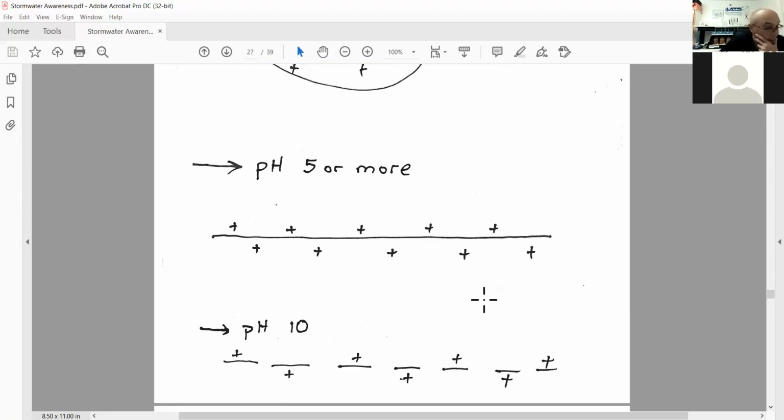So chitosan is pH sensitive and therefore needs to be used in pH ranges that are conducive to construction stormwater discharge requirements. When pH is 9 or above, chitosan will not work as well as at 8.5. At pH 10, the molecule is severed and doesn't work.